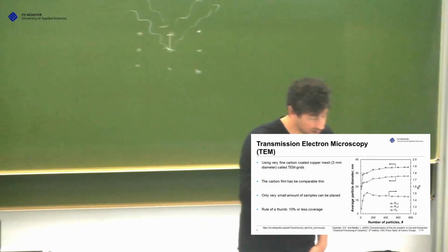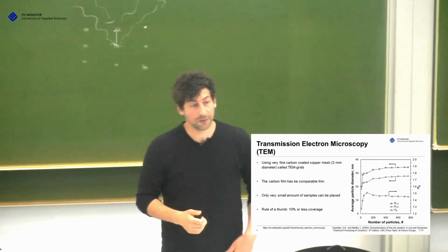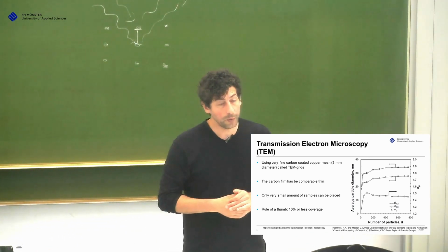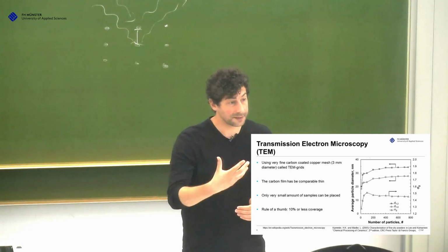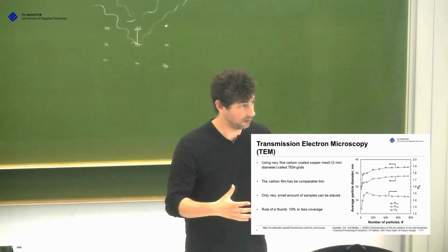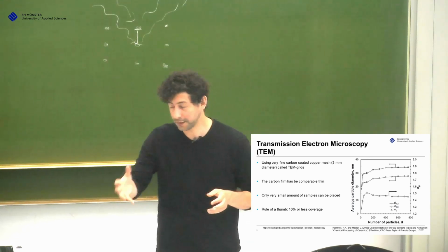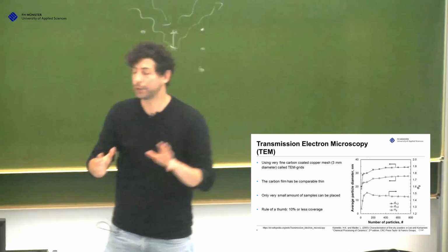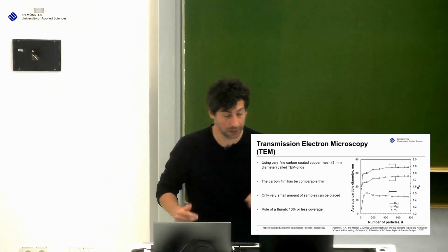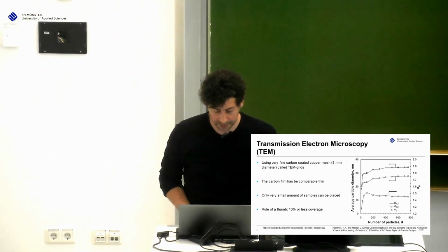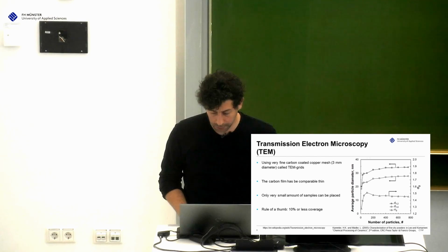And this is also something not only for particle size, but if you make any measurement, always be sure that the number you counted or whatever is statistically relevant, okay? If you just count 5 things and then say, that's my number, be sure if 5 is a good number to count, or if you need 50, 5,000, or whatever. And for particle size and TEM, we have a clear knowledge about it.